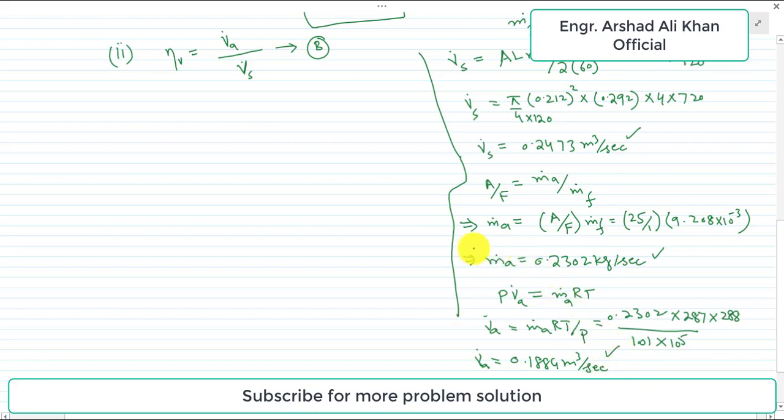So now both values are known to us, that is the swept volume flow rate and the air volume flow rate. Simply putting these values here in this expression B, volumetric efficiency is equal to 0.2473 divided by 0.1884 cubic meter per second.